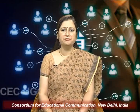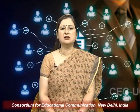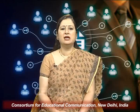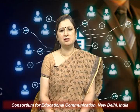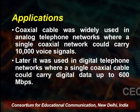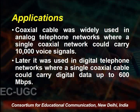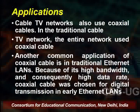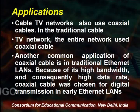Now applications of coaxial cables, they are widely used in analog telephone networks, where a single coaxial network could carry 10,000 voice signals, and then later on it was used in digital telephone networks also, where a single coaxial cable could carry digital data up to 600 Mbps. So coaxial cables have been widely used in cable TV networks, and in telephone networks, both analog and digital, and cable TV operators of course use it.